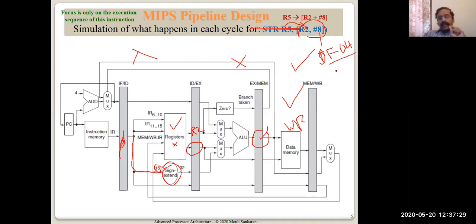So if I need to perform a 32-bit addition, I should make the 16-bit value into a 32-bit value, which is sign extended. If the sign bit is 1, I should extend the sign bit as 1. So I should put F, F, F, F, F. Okay. So this is the 32-bit value offset, which is getting computed from the instruction and fed to the ALU.